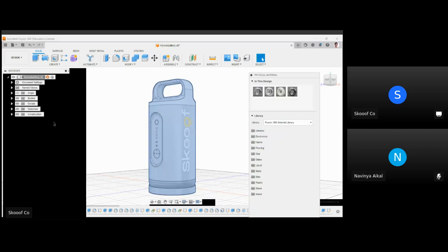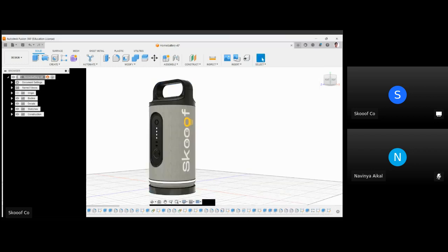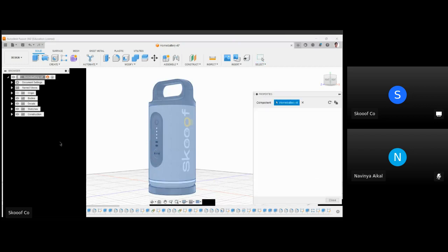To do that, you have to click on, sorry, I opened it. So to do that, you have to click on properties. There is an option here. So click on properties. It will generate. It will take maybe a few seconds here. See, now we have the material as varies because all types of material you have used here. Go to physical and you will find all the details.